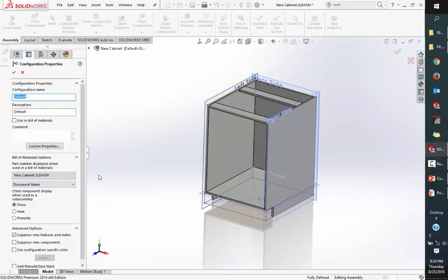But yeah, that's the other thing. You get into some dicey situations with bills of material, and sometimes it's a little tough to manage. That's when I use configurations. I'll make a BOM configuration and put all the cylinders in using the same configuration. Right. That way it rolls up my quantities correctly. Yeah, most definitely. So, yeah, we can definitely take a look at it. If you're having that issue, just give us a call and we'll see what we can do to help out. So, any other questions?